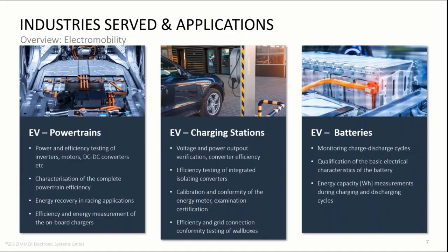Also on EV powertrains, we often see regenerative braking. Both electric and hybrid vehicles use this method to utilize the energy which is returned from the wheels to the motor during braking to charge the battery or provide quick acceleration, which is especially useful in racing applications. Here, power analyzers allow powertrain engineers to monitor the bidirectional power flow between wheels and battery and assist them in